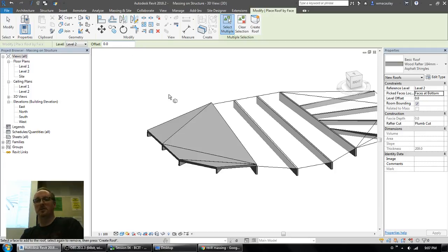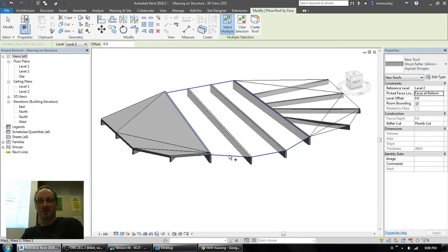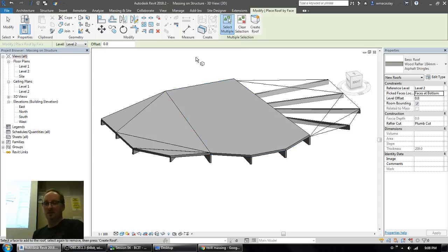These massing tools can help you, especially with roof geometry, to solve some of the modeling problems that you just couldn't otherwise accomplish. So if you're doing timber structures, especially something like this, which is kind of like a West Coast sort of Denman, Hornby Island style construction, stuff that Blue Sky would build, or one of those other firms, designers here on the coast. This allows that kind of geometry to be easily placed on top of what frankly is easy structure to put up. It's easy to put those beams up at different elevations. It's just hard to model the roof that would go on top of it. So by using the massing tool set, we can build that geometry on top of these roofs.